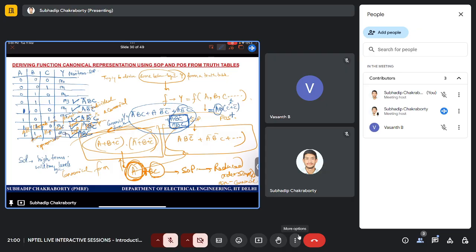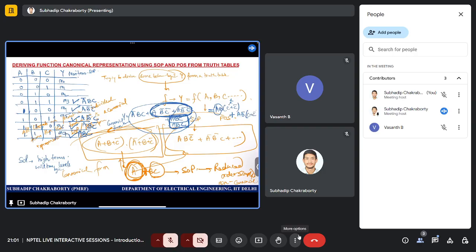Plus let us take which two terms? Let us take these two terms, you see my marking. Let us take common A B bar out of these two terms. Again we are left with C plus C bar, which is nothing but 1, plus A bar BC. So what we are left with is AB plus AB bar plus A bar BC.